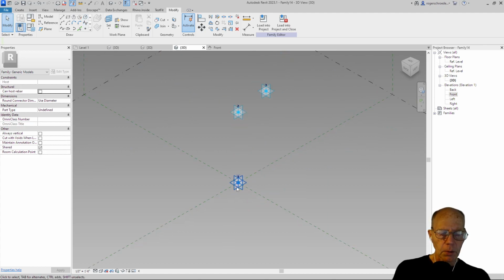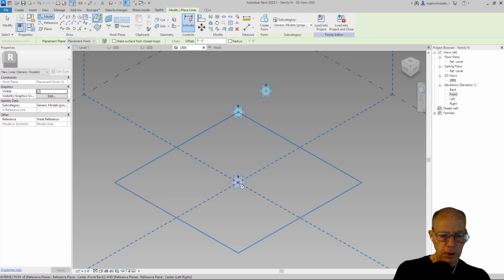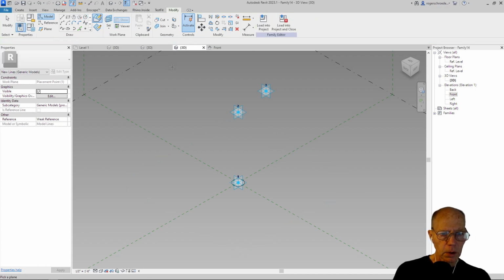So now we want to establish the base circles that we're going to extrude from one to the next one. So I'm going to start at the very base, select that base plane, create a circle, and I'll make this, we'll do 18 inches. So I'll make it a 3 foot. I'm going to set the next one up.